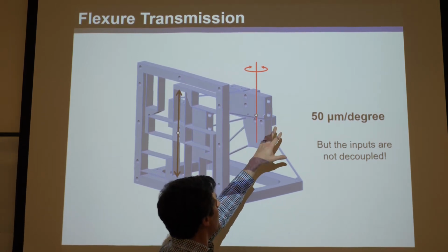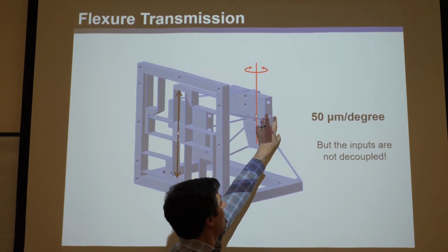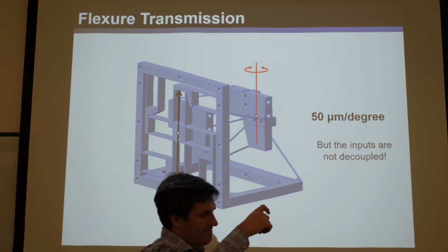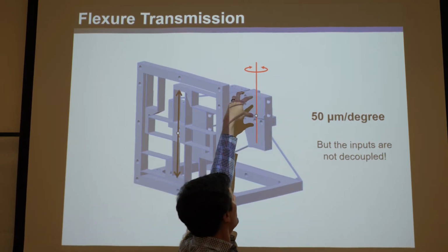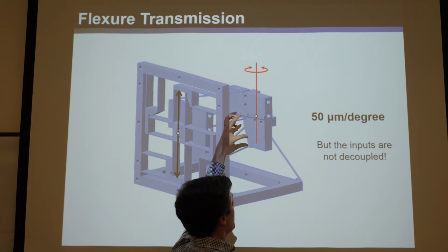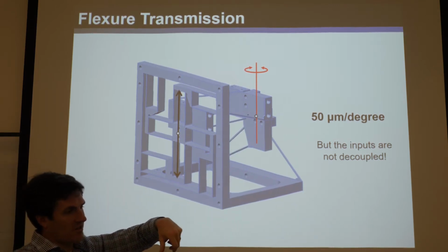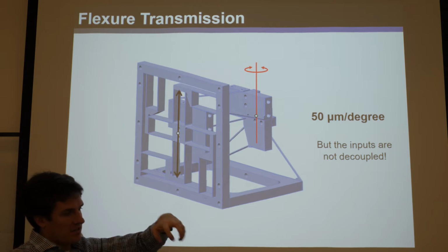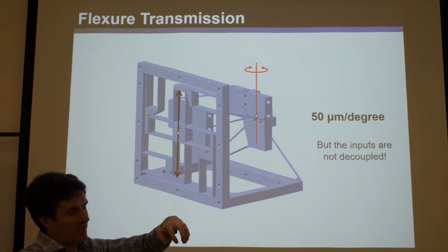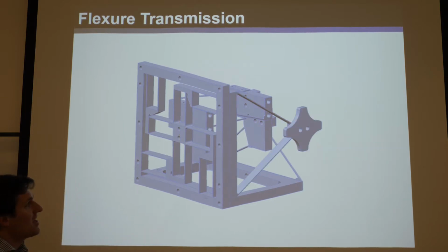And that's no good. Like if we just stuck the handles on there and there, when we rotate that one, this handle's going to rock over, and that's very unpleasant. If you want to rotate this one, you don't want the other one to be moving. You want to just have the handles stay put and independently rotate them. So what we need to do is put a handle floating away from here and attach it to ground here.